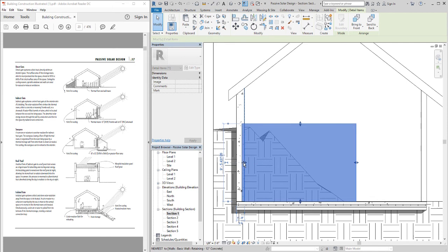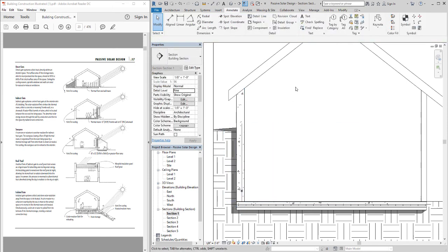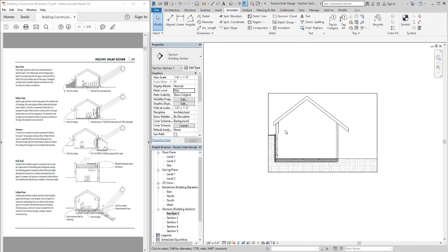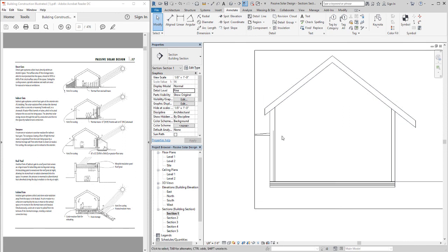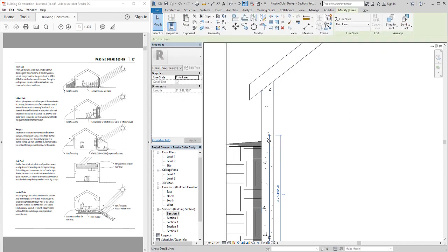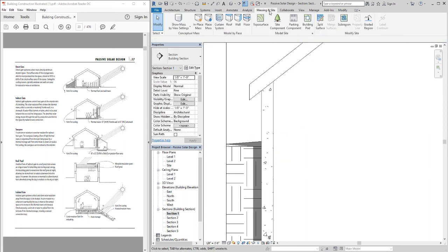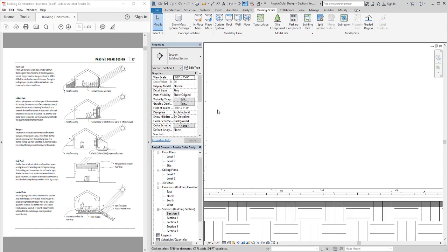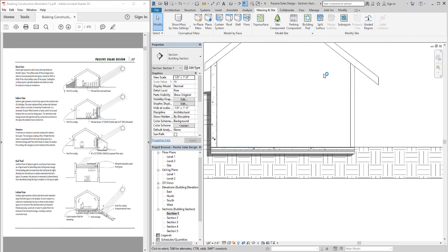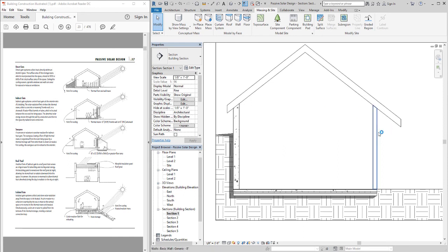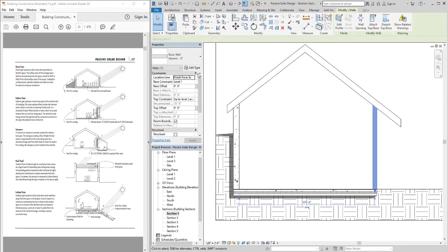a quick way, a masking region to just hide that out. I could have also dug that out, excavated that with a massing and site tool, and you could basically trench in a building pad into this location, and then I wouldn't have to use the masking region. That's a quicker way. Alright, now this wall here pretty much needs to become a curtain wall.